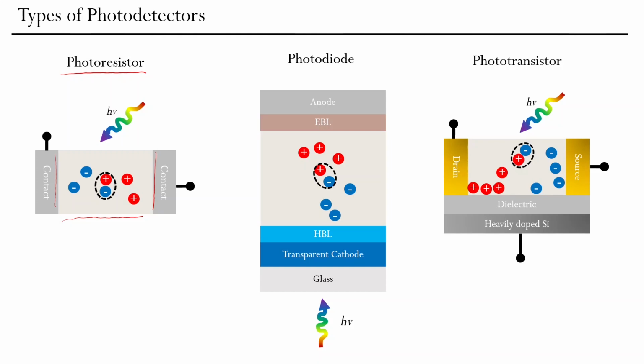Another is the photodiode, which is actually the same as a solar cell, because every solar cell can work in photodiode regime. It's just a question whether it will be the best photodiode, but it can work as a photodiode. It's designed for different purposes, to operate in photovoltaic mode, but it can always operate as a photodiode. And obviously every photodiode as a PN junction can operate as a solar cell in photovoltaic mode, but obviously the photovoltaic parameters will be quite low.